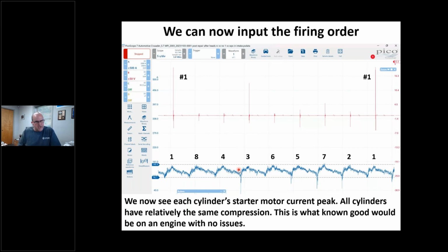Pretty handy. You know, I work on a lot of marine engines. Marine engines are wedged in there, some of these boats. I see guys taking 16 spark plugs out, checking compression on 2 engines. That's a lot of work. I got an engine that doesn't idle right or doesn't seem right, or maybe I got crankcase pressure issues. Okay, if I'm a diesel engine, since we're touting this as a diesel webinar, if I have a piston that's maybe cracked or got a hole in it or something like that, I can maybe catch this here.